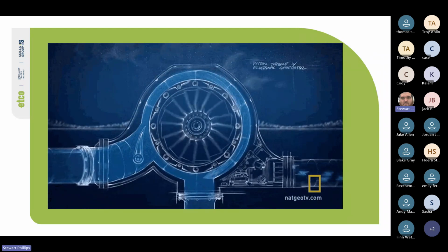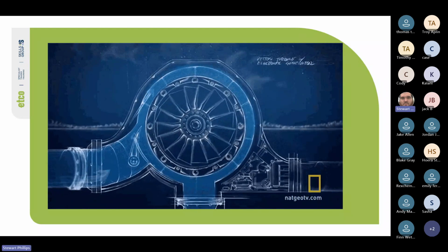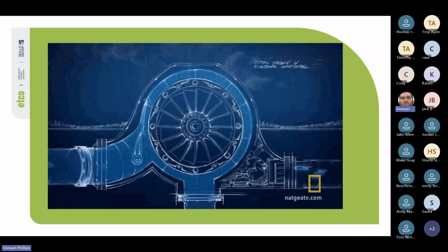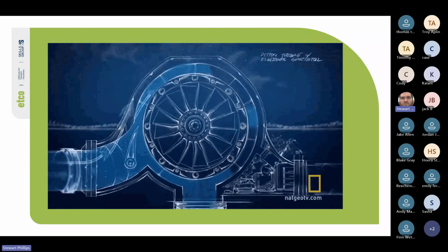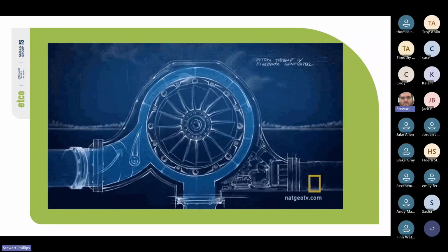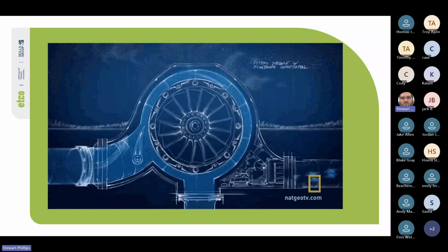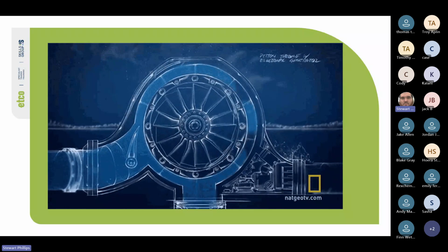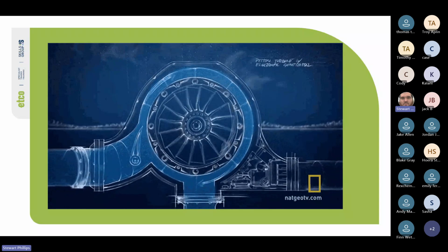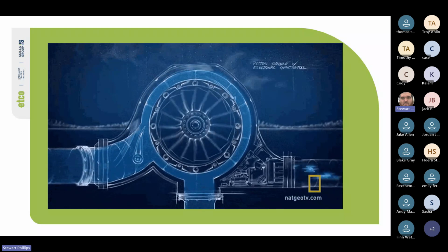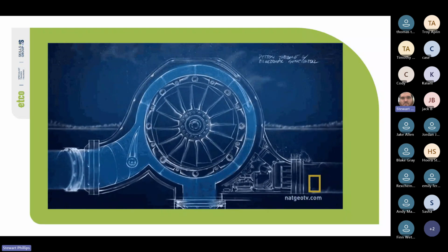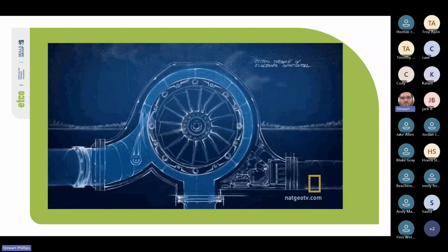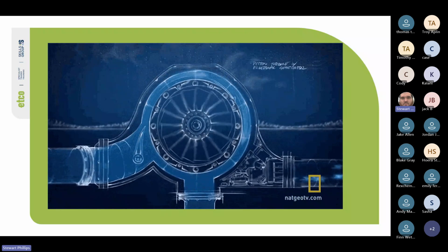Yep, so Troy already got the nail on the head. Due to inductance, but things are different for AC. Imagine that same flow of water is constantly going back and forth, pushing the turbine from both directions. The turbine would never get a chance to get up to speed and would constantly be opposing the flow of the water. It's similar to what happens when we pass current flow through an inductor or a coil of wire in an AC circuit.